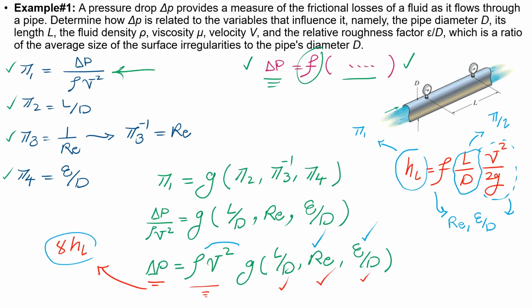So this is how Reynolds number was developed, and this is how they found out that whenever you have a pipe system problem, what to look for. And that's why that's the Darcy-Weisbach equation in combination with Moody diagram that you use to find head loss in a pipe. And remember that we wanted to find how delta P relates to other variables such as diameter and velocity. And for that purpose, we found 4 dimensionless numbers, and based on these dimensionless numbers, different researchers, different scientists did lots of experiments to find out the Moody diagram that you are using right now easily to find out different friction factors and Darcy-Weisbach equation as well.